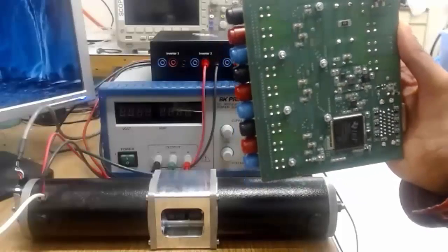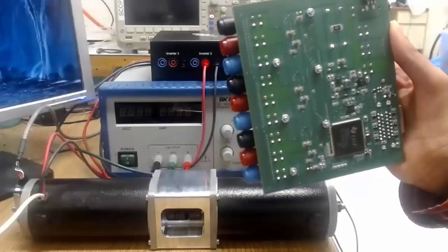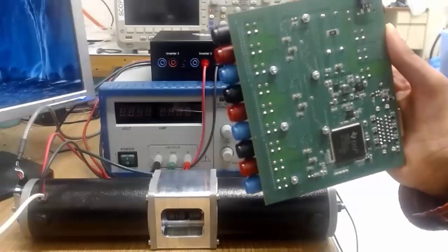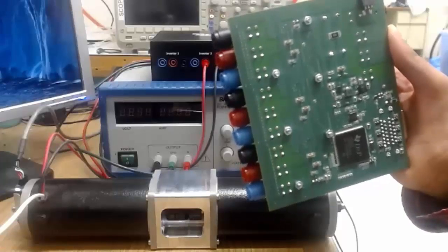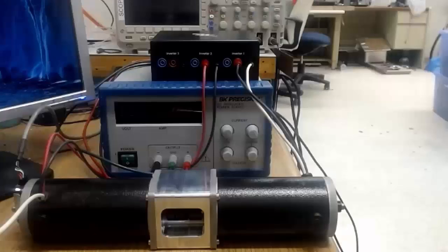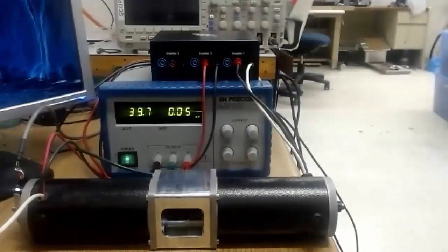The onboard programmer and the data logger allows any model developed using Workbench to be directly programmed into this controller, and it also allows us to vary any data on the microcontroller in real time from Workbench and also measure and log any data from the microcontroller back onto Workbench through USB connection. Let's go ahead and run the system in real time. We are using a standard 42 volts 5 ampere DC power supply to power the inverter module.